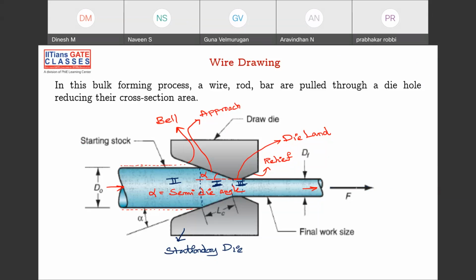Fine. So please remember, again I'm saying we are trying to pull from the exit. We are not doing anything here. Sometimes we are pulling this side also, that is called the back stress, but mostly we'll avoid it. Sometimes we'll use this back stress. I'll tell you why we are using this back stress anyways. So we are pulling this, so here only we have to calculate this drawing stress.